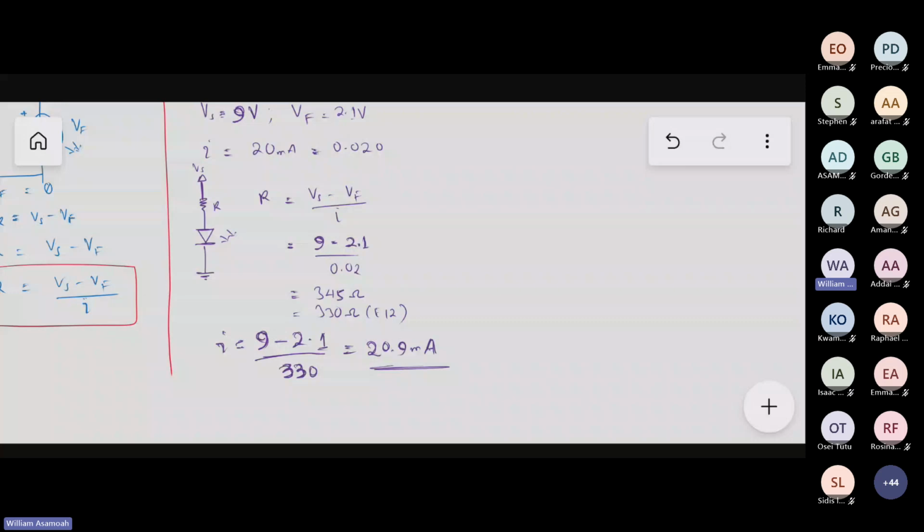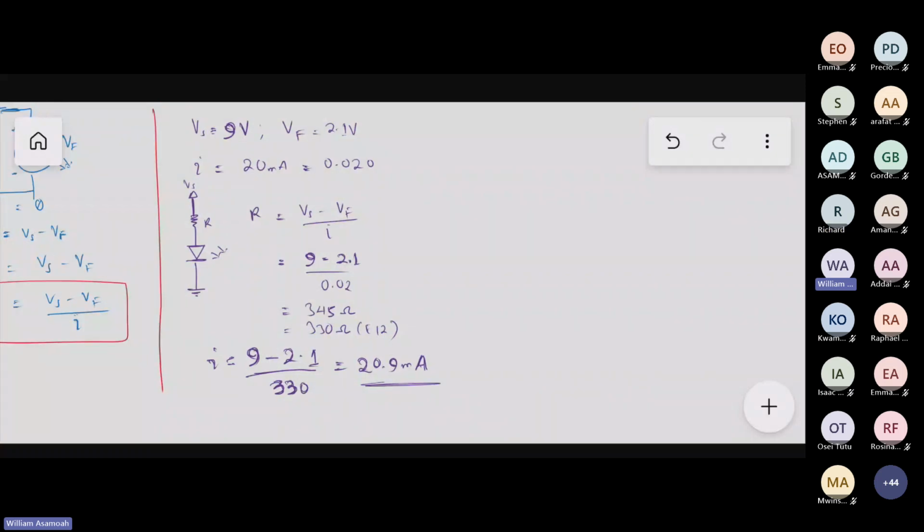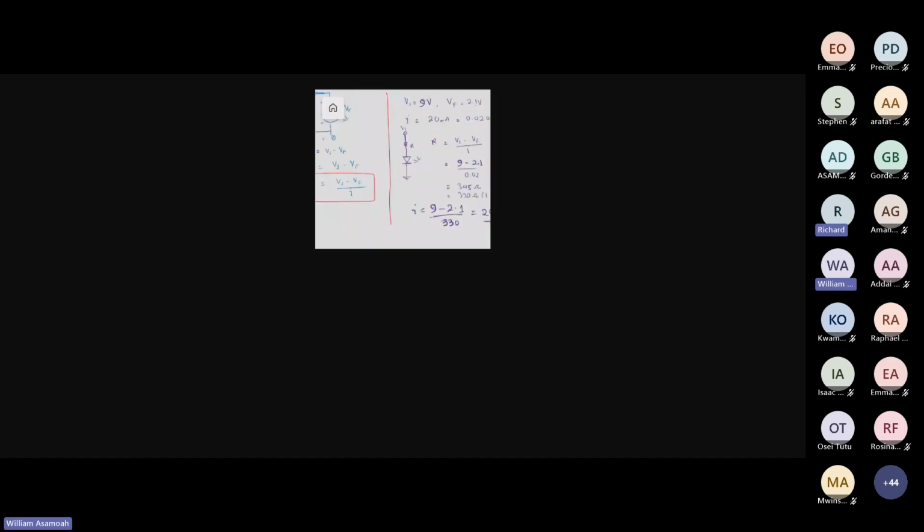But if you calculate the power rating here as 0.24 watt, a quarter watt is a bit close. When 0.24 is within the safety margin, this device will spoil quickly. So a careful designer would choose a 0.5 watt rating. That will make it expensive, but when you buy it, you use it for long. But the Chinese manufacturer is cutting down cost, so he'll give you that 0.25. As long as the thing is working, all right, but the lifespan of the resistors is very, very short.